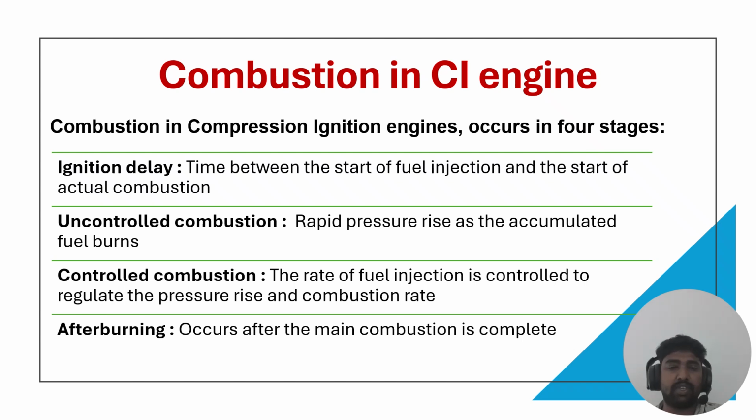Now if we look at the four stages, ignition delay is the time between the start of fuel injection and the start of actual combustion. Uncontrolled combustion is where we see a rapid pressure rise as the accumulated fuel burns in the cylinder. Next is controlled combustion, where the rate of fuel injection is controlled to regulate the pressure rise and combustion rate. And the last stage is the afterburning stage, where the main combustion event is completed.